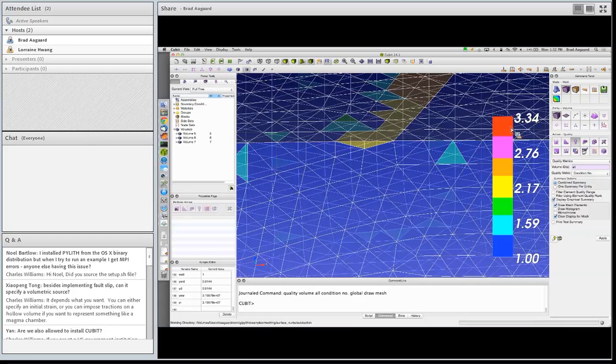It's locally it'll be stiffer. So it will affect the solution locally. Globally, it'll affect the rate of convergence. So it's mostly the rate in a quasi-static problem. It's mostly the rate of convergence that you'll see, and then locally you'll have a slightly stiffer cell in that local region. So your solution in that region won't be as accurate as what it would be otherwise.